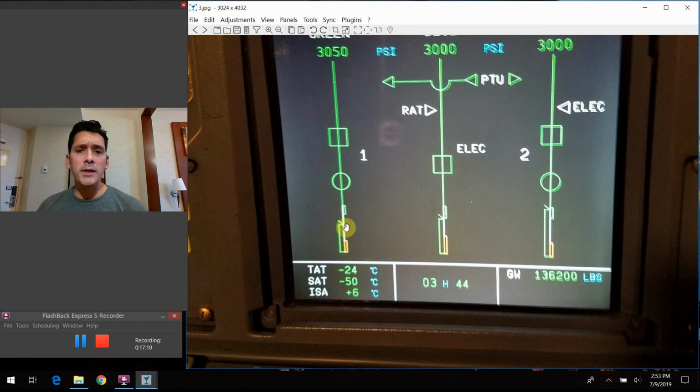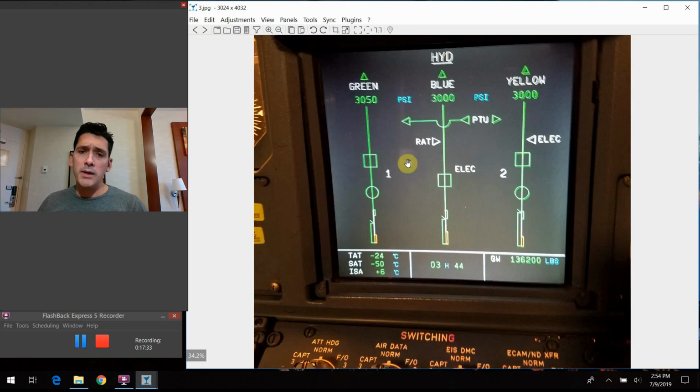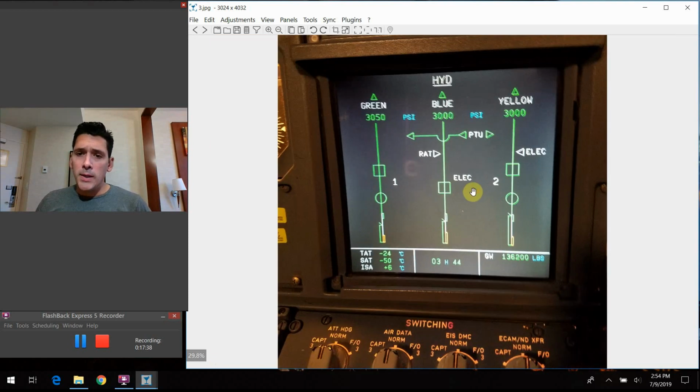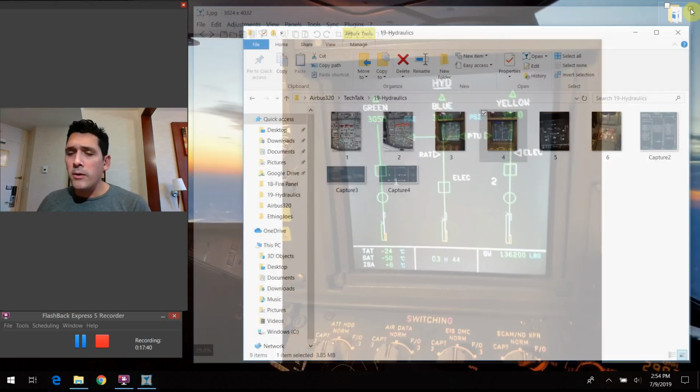And the reason is because the landing gear being such a big system, there's actually a certain amount of fluid that works its way into these hydraulic actuators and just resides in those areas during the cruise portion of the flight. So when the gear is up, you have this different quantity reading that's registered by the airplane. It's seen in the reservoir, and that is the reason why it looks that way. So just some high level stuff there.